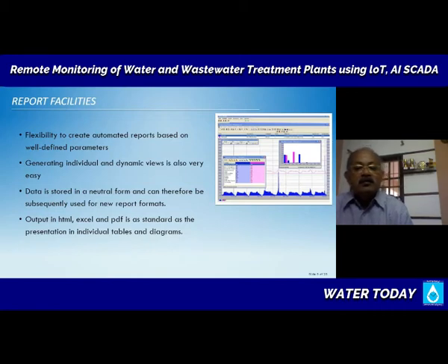So if there is any maintenance due, you can plan for that. These systematic operation and maintenance practices can be established using these systems, and you can do things which are event driven, because the events are available, known, noticed, and recorded. You can be controlling things based on an event. When you are monitoring and you are having surcharges every day at a specified hour, and you know when your peak flow is coming, you can think of a way of handling that.